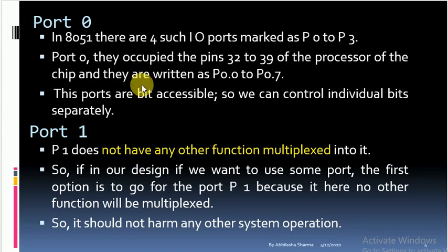One function of this port is as an IO port, used for read and write operations for general purpose. The other function is as the low byte address and data bus for external memory design. So port 0 is used in a multiplexed form.